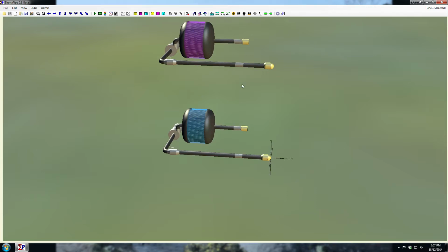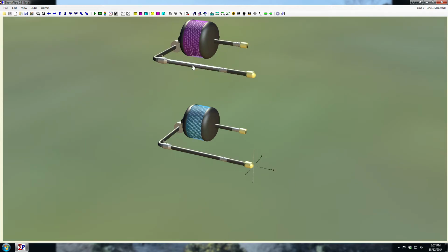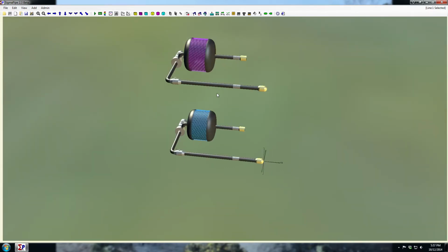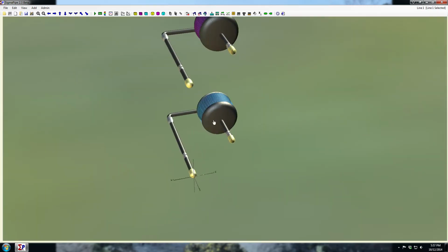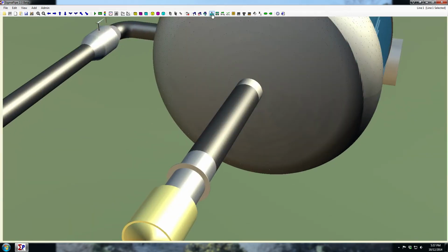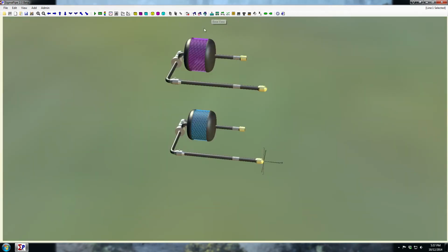Well, one thing I forgot to mention before was if you have quite a complex or any system and you have a nice view where you can view everything, if you hold Control and press this base view button, it saves your current perspective as in that button, and then if you go somewhere that's quite hard to find everything from, and then you press base view again, it'll take you back to that starting position.